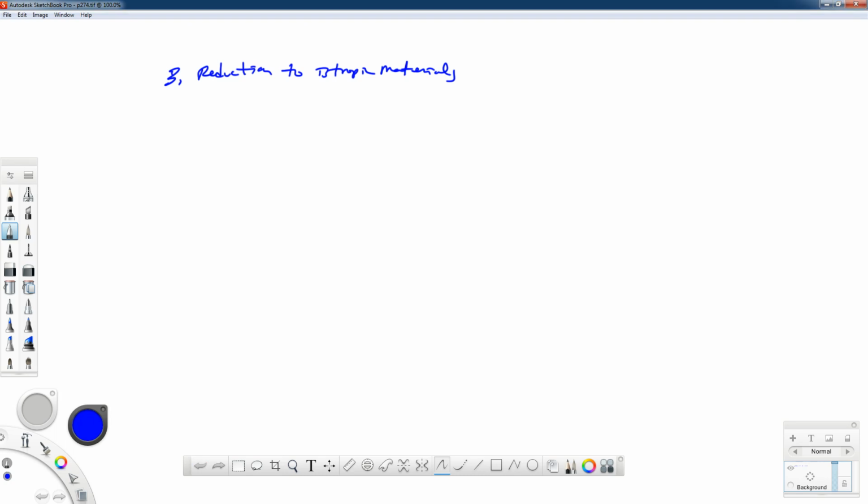Now, we mentioned in the previous lecture that if we had a material that didn't depend on direction, then we can write the strain energy density function in terms of the principal strains. So U would be a function of just the principal strains, which I'm going to call here, with our book's notation, epsilon 1, epsilon 2, and epsilon 3. So it doesn't depend on our eigenvectors, doesn't depend on our 3 angles that we might use to describe our strain energy density function.